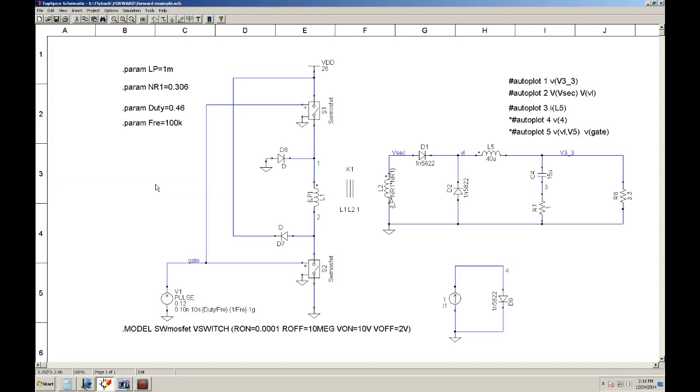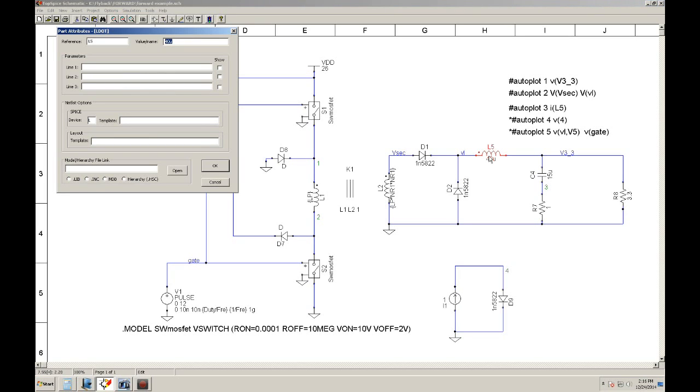Okay, so I think I have everything here. And let me see. And here is the 1N5822, which is a Schottky, another Schottky. And right now, I'm not simulating for ripple. I just want to get a plot of the waveforms. In the next lecture, I'll show you how to set or design the output inductance. Okay, and I believe that's about it. So I need to change this to 196, I believe.